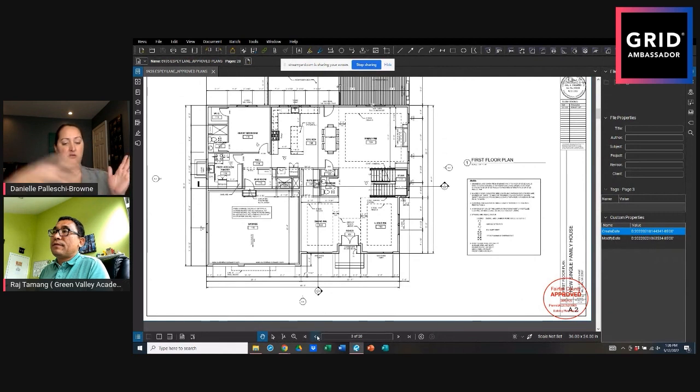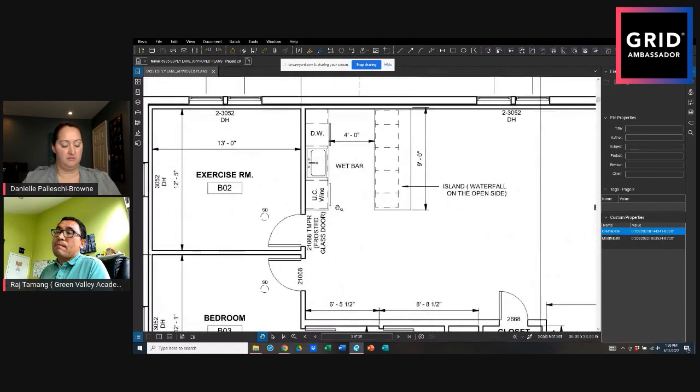So it's really based on how you would open the door into the room or into the building. Typically, in terms of operation, how the door would operate is in-swing or out-swing, right hand or left hand. That's how you're going to tell them when you order the window or door. You can give them a drawing, but if you need to order the door, you just say, I need a 2 foot 10 inch door, 6 feet 8 inch high, in-swing, right hand, or whatever it is.